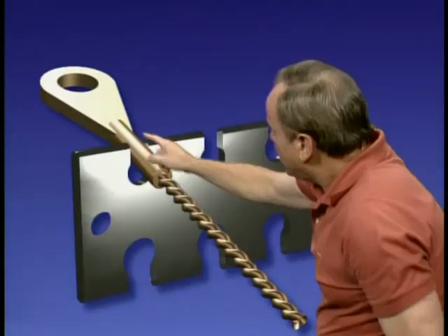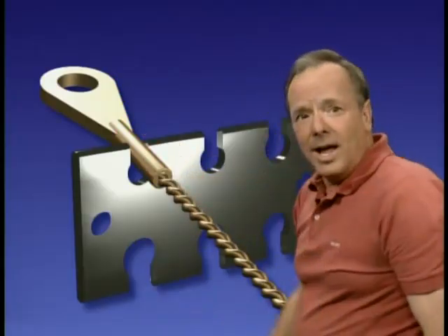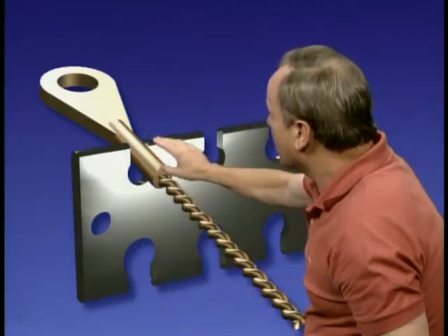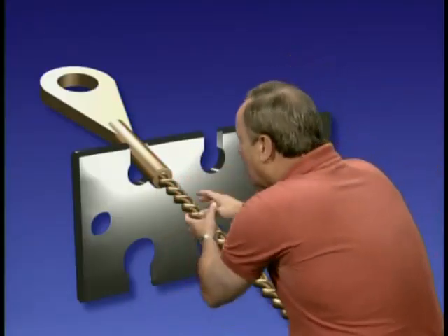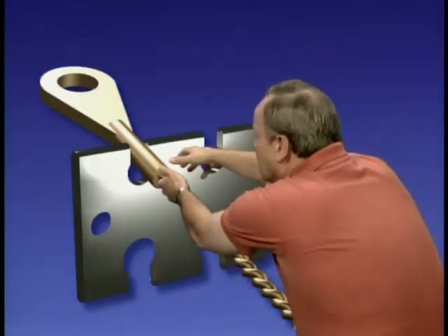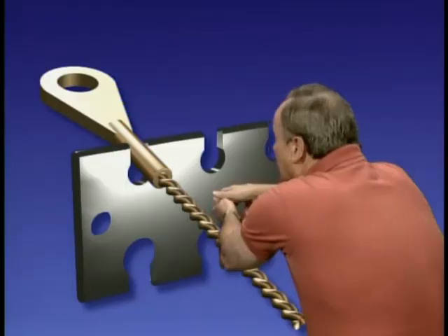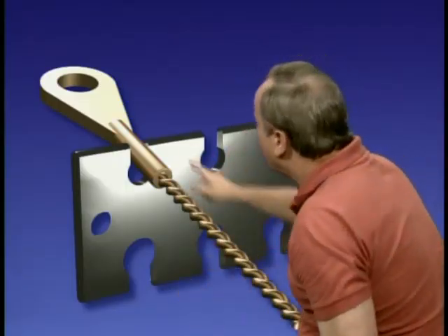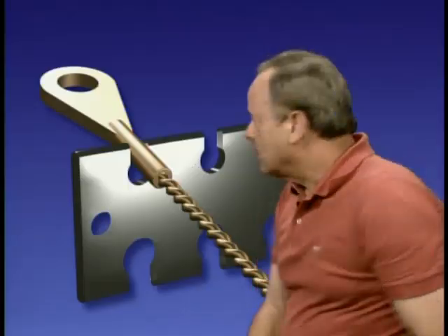Now, when you put this thing together, you want to make sure it lasts. Well, corrosion treatment, it's a good idea. It's not required, but that's one of the things you can do. But the real thing you're concerned about is is it strong enough? Well, one of the things you can do is what is called pull or load testing to 60% of its breaking strength. And that's required, but that still doesn't show you that you met the manufacturer's requirements for swaging it on. Well, one way to determine that is just this.